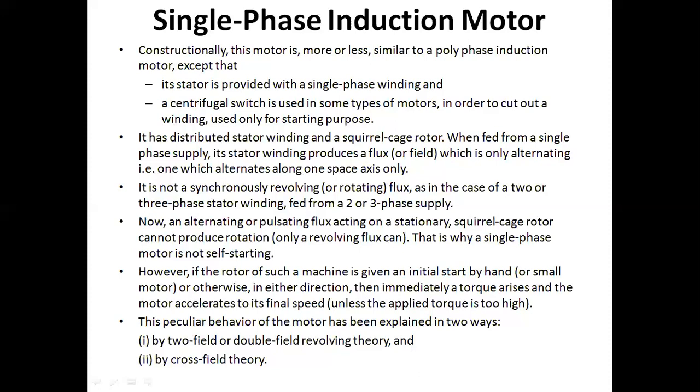Okay. Now, constructionally this motor is more or less similar to the polyphase induction motor, except its stator is provided with a single-phase winding. First thing is, the stator is provided with a single-phase winding, and a centrifugal switch is used in some types of motors in order to cut out the winding used only for starting purposes. Another important thing is, the single-phase induction motor is not a self-starting motor.